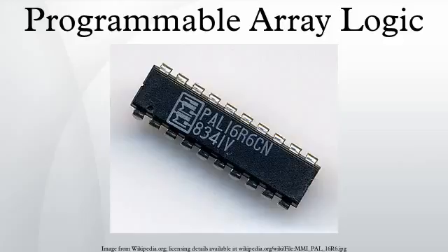Each output could have up to 8 product terms, however the combinational outputs used one of the terms to control a bidirectional output buffer. There were other combinations that had fewer outputs with more product terms per output and were available with active high outputs. The 16x8 family of registered devices had an XOR gate before the register. There were also similar 24-pin versions of these PALs.